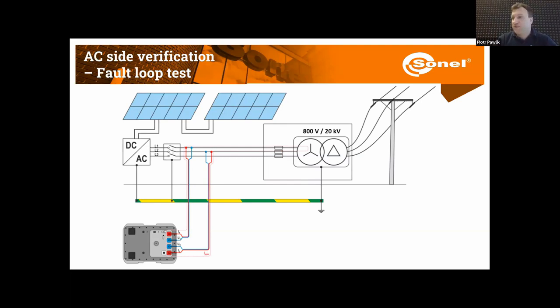So that's why we need to do that. And we do this test on live installation. And in case of photovoltaic installations, it may happen that the transformers will work at a voltage on the low voltage side which is higher than the regular 230 volts. So that's why when selecting the meter, we need to check its operating voltage to be appropriate to our system.